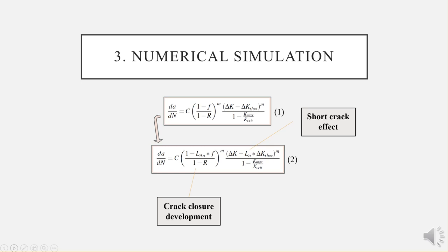This selection is rather arbitrary, so some controversy appears. The model used in the present work allows one to calculate fatigue life as a function of that initiation length, and by the end of the process, we can choose the most conservative result. This model has been used several times before, yielding very good results. Let's focus on the propagation phase, which has been slightly modified for the present research.